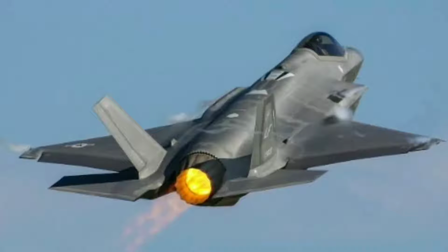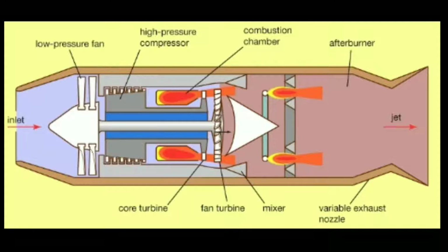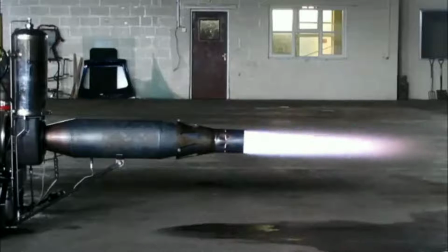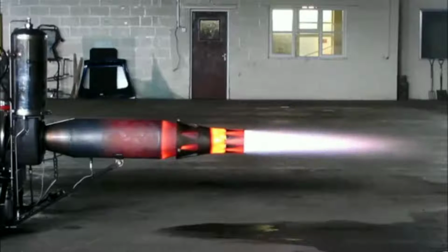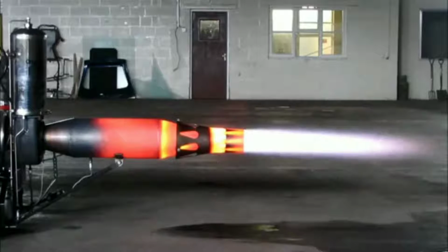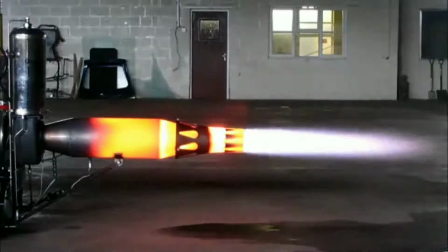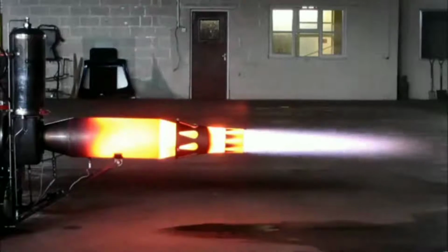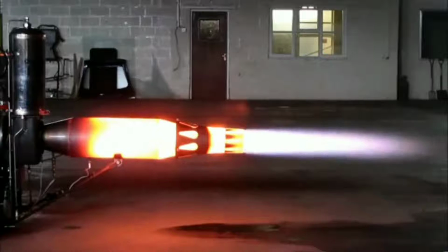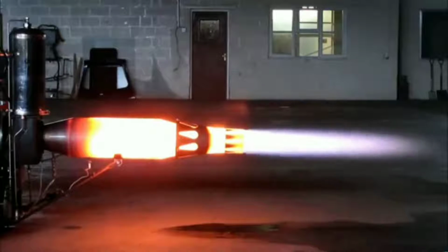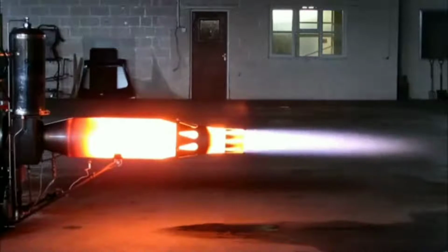An afterburner is used in jet engines of military supersonic aircraft. An afterburner increases the thrust without any additional weight of the engine, but at the cost of high fuel consumption and decreased fuel efficiency. An afterburner injects fuel downstream of the turbine and reheats the gas. As a result, temperature rises in the tailpipe and gas is ejected through the nozzle at a higher velocity. Mass flow is also slightly increased because of the addition of the fuel at the end.